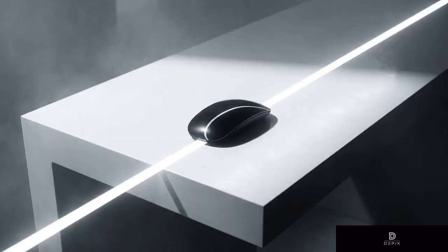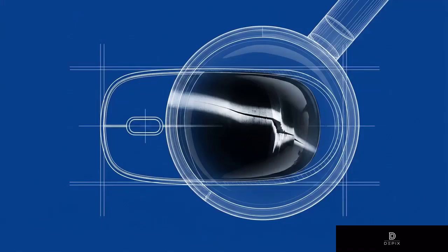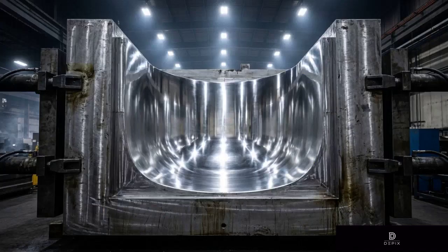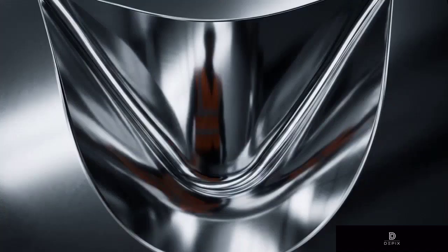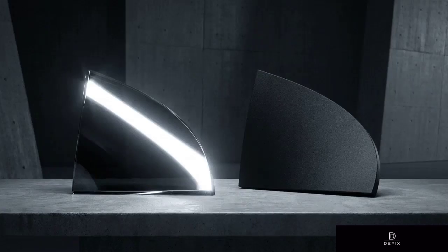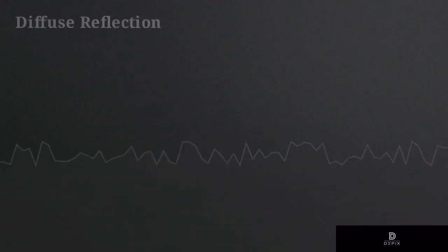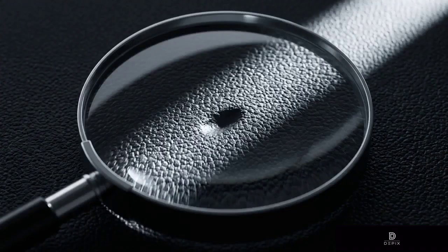That is why achieving a Class A surface in industrial design is an exacting standard of aesthetic reflectivity under light, rather than a standard of physical shape. Out in the manufacturing pipeline, producing a high-gloss injection molded part requires a diamond-buffed tool. That highly polished steel acts exactly like a mirror, amplifying every hidden geometric flaw in the plastic underneath it. If you specify a matte or textured finish instead, that exact same tool grade isn't required. The rough surface actively scatters the light, masking flow lines, hiding knit lines, and minor structural defects.